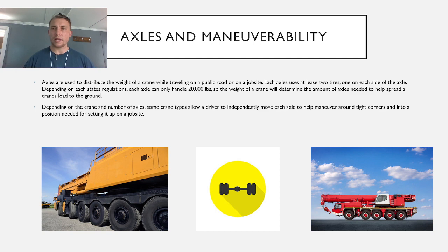The smaller the crane, the less axles are needed. And then if you only have a certain amount of axles, you might not be able to put counterweights on the back because you don't have enough axles, or it might put too much weight on an axle. So the axles itself are very important for traveling on the road.